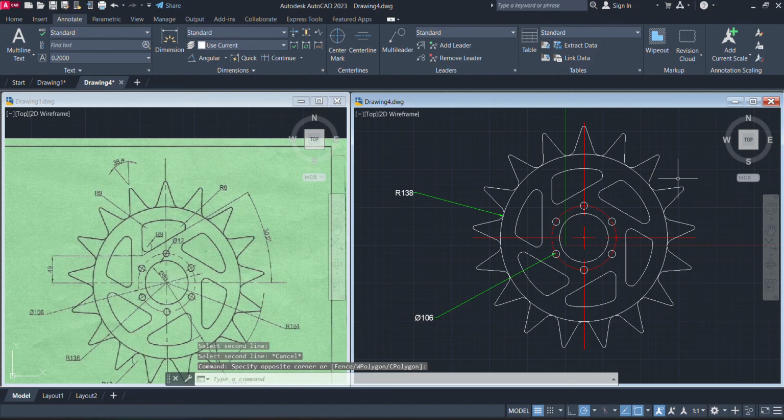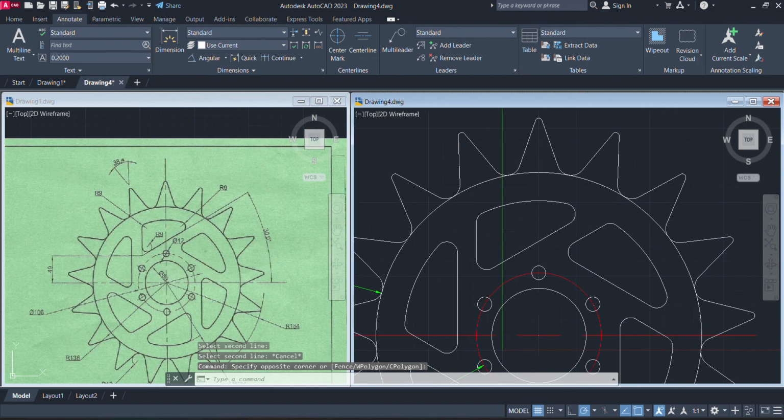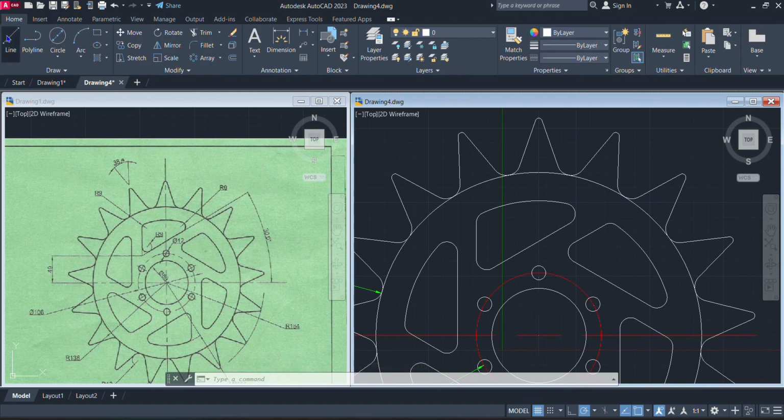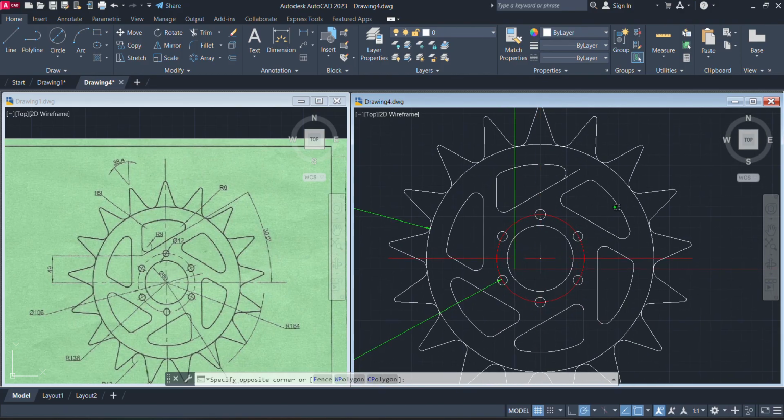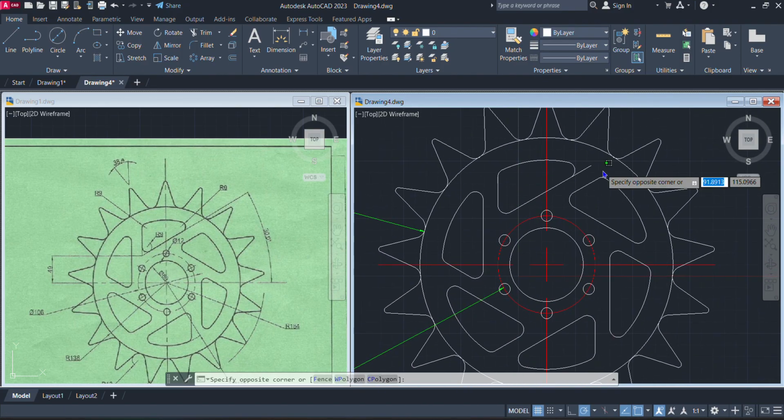So what you do, you can just zoom in, then you create an extension line. I can click line command, then I click there and create an extension line, and that line you should make sure that it is slant by 30, so it is just a continuation of this side. This extension line will now enable me to enter the dimension.